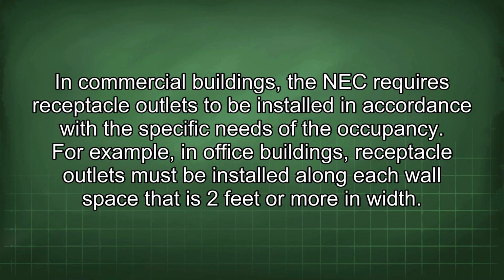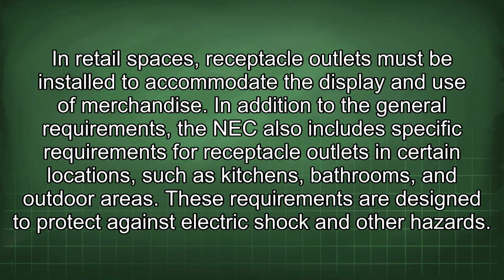In commercial buildings, the NEC requires receptacle outlets to be installed in accordance with the specific needs of the occupancy. For example, in office buildings, receptacle outlets must be installed along each wall space that is 2 feet or more in width. In retail spaces, receptacle outlets must be installed to accommodate the display and use of merchandise. In addition to the general requirements, the NEC also includes specific requirements for receptacle outlets in certain locations such as kitchens, bathrooms, and outdoor areas. These requirements are designed to protect against electric shock and other hazards.